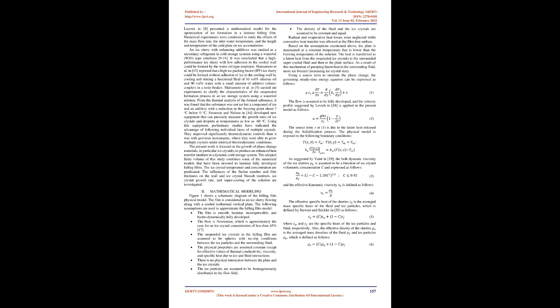transfer. Kozawa et al. in [7] investigated the effects of ice content, ice packing factor, IPF, and mass flow rate of supplying ice slurry on the ice storing characteristics in a tank. It was found that by raising IPF and reducing the mass flow rate of supplying ice slurry, the ice-rich layer was hard to spread horizontally in the tank.